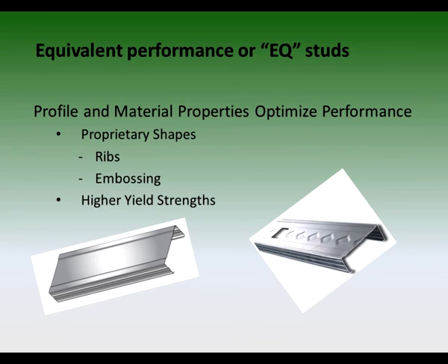Moving on to an EQ stud, the most basic definition is that an EQ stud is a stud that is similar in shape to a standard C stud, but has some unique features about it that allow for thinner sections while still meeting the same performance as a standard stud. Thus, the EQ or equivalent designation. EQ studs are proprietary to each manufacturer.